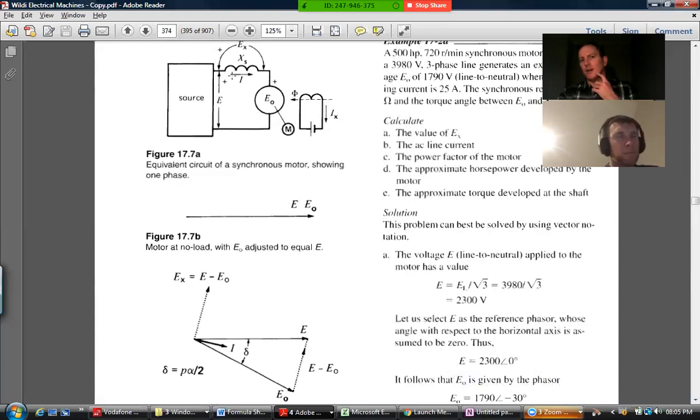Of course, it's a bit strange, because we know that this is AC. So these things are changing polarity all the time. Well, in fact, this one's not, is it? That point there is actually the neutral, and we're drawing this per phase. So technically, this one is staying zero. It's the start point. And this one is changing. It's going above the start point and below the start point, above and below. But these arrows, these vectors, give you a snapshot in time.